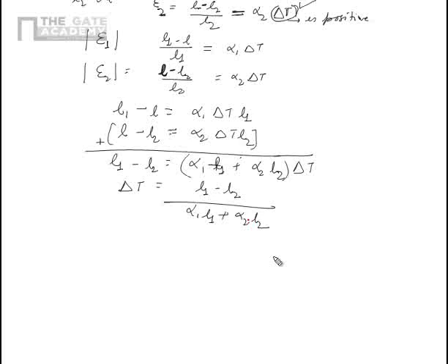But that's non-physical, because if there is no cylinder inside, you cannot shrink an existing cylinder to 0 length just by a temperature change. That is like not following the conservation of mass, because suddenly the mass of the cylinder cannot vanish. So obviously these equations have to be applied with a lot of caution, which is that we simply cannot apply them without understanding what they mean internally.